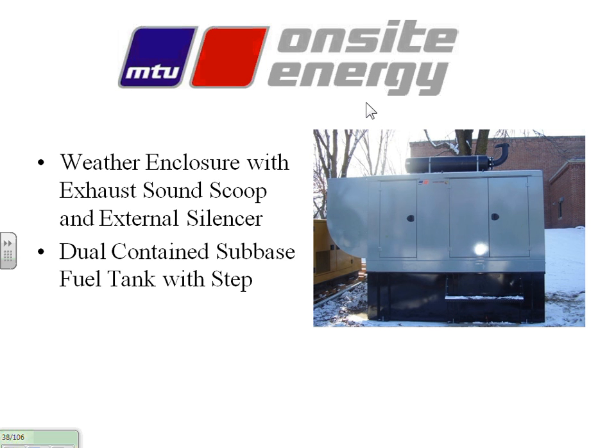This is a form of noise attenuation. In other words, we're going to make this set a little quieter because noise travels in a straight line. If I didn't have this scoop on there, that radiator would be right there, and it'd be kind of noisy because it's going to come right out of there. It's in a straight line. So we direct that air up, and that's a form of attenuation. And because we don't want rain and stuff, we put slots down here in the bottom of this scoop, so anytime it rains or gets snow in there, it can drain out the bottom.